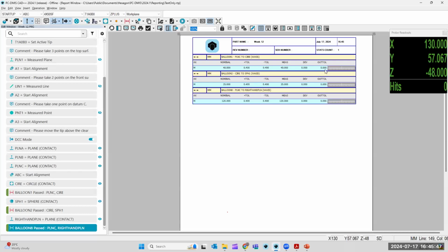If you see out of tolerance, that's where you say, okay, there's a problem with this part, and I need to tell the customer this part is unacceptable. So it gives a nice red bar here, which I can only show online as well. It'll be red because it's out of tolerance, either large or small, or plus or minus. And the variance from nominal will show in different colors. So a good measurement right near the middle is nice and green, and then you get dark green, and then you get yellow and red.